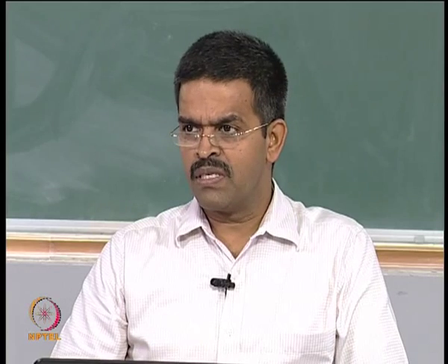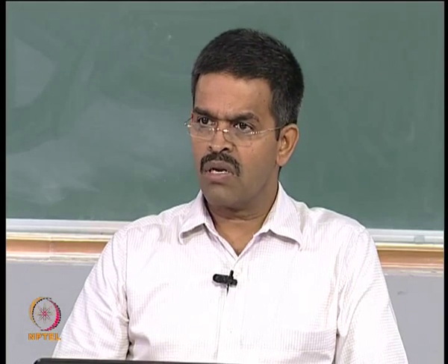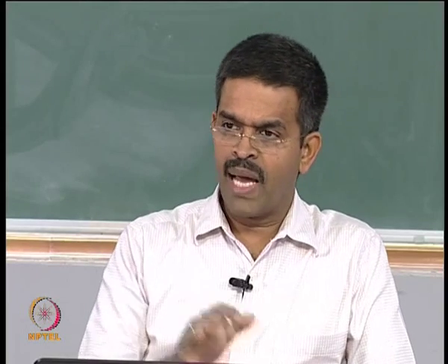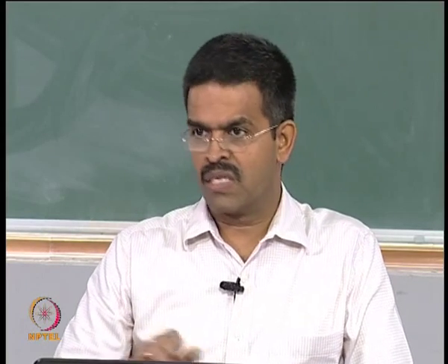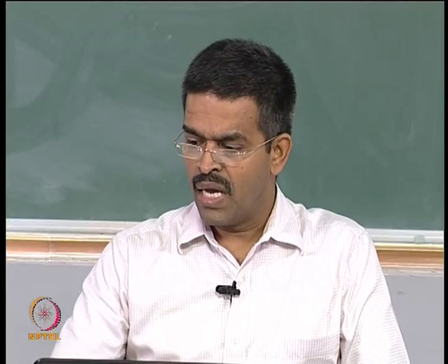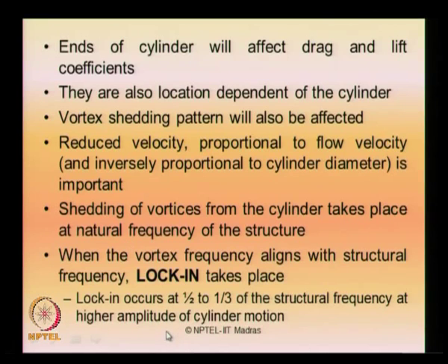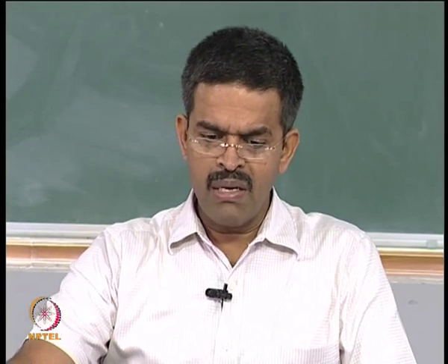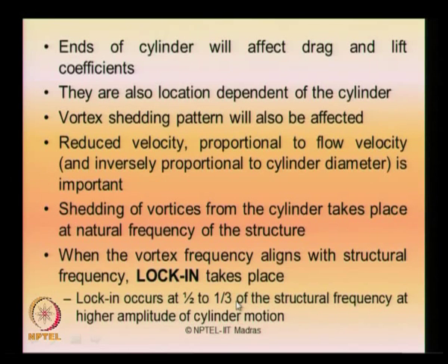Essentially, ladies and gentlemen, please understand, resonance does not occur only when the forcing frequency matches the fundamental frequency of the structure. It can also occur at about 30 to 50% of the structural frequency. If this occurs because of vortex frequency, this is what we call lock-in. Lock-in is a very dangerous phenomenon because the amplitude is increased significantly at these kinds of frequencies.